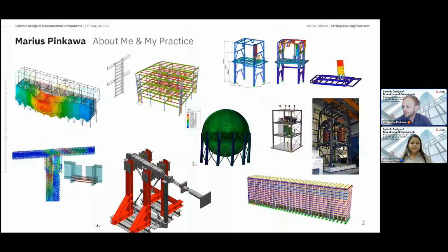So we have to tear down the building and then rebuild it. But a more sustainable approach is to have some specific elements in the structure, like these beam links here. So they dissipate the energy, and after the earthquake, we can replace them, and the building can still be the same, so we don't need to replace it.